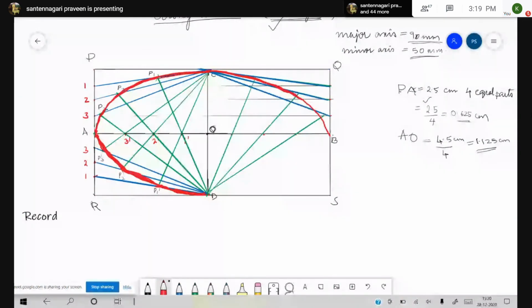Okay. So the same on the other side. Finish off the curve. I'm doing it simply, don't do this. You have to draw the other box also. The same similar lines, you have to draw it and join them. Then you will get the complete figure. Now this red curve looks like an ellipse. This is your construction of ellipse by a special method called oblong method or rectangular method.